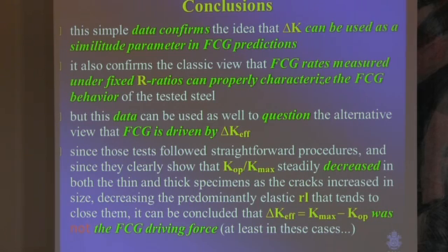So, the only thing I can say here to avoid the huge discussions we had in Urbino is try by yourself. I don't know how to do better. I have used 4 independent measurements of the opening load. The only thing I have not made yet is to use tomography to see how the crack opens along the crack. I'm going to do that next, but I have to use an aluminum alloy because my tomography is not powerful enough to work with steel.